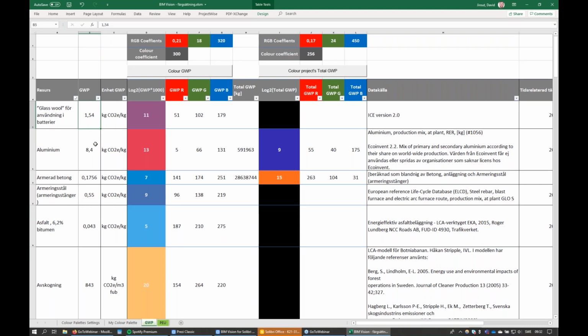The life cycle stages follow the norm called ISO EN 15804, and there are 17 life cycle stages out there. In this case, we have carbon numbers for life cycle stages A1 to A3, the sum of these 3 stages, which means the production of the product.